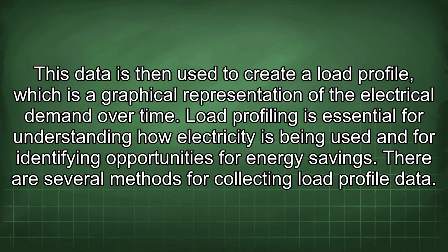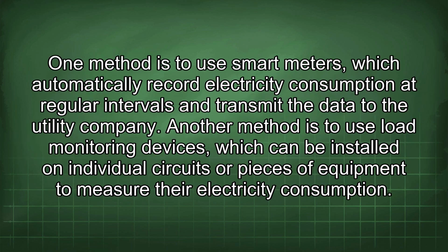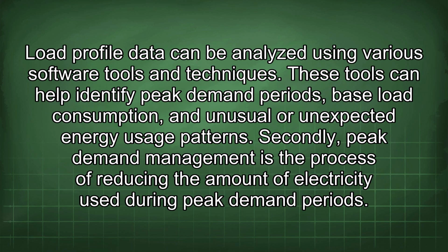There are several methods for collecting load profile data. One method is to use smart meters, which automatically record electricity consumption at regular intervals and transmit the data to the utility company. Another method is to use load monitoring devices, which can be installed on individual circuits or pieces of equipment to measure their electricity consumption. Load profile data can be analyzed using various software tools and techniques. These tools can help identify peak demand periods, base load consumption, and unusual or unexpected energy usage patterns.